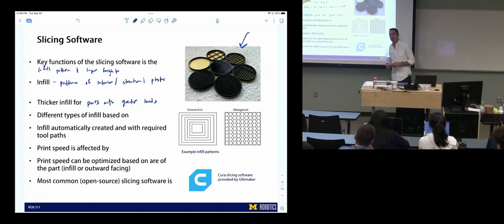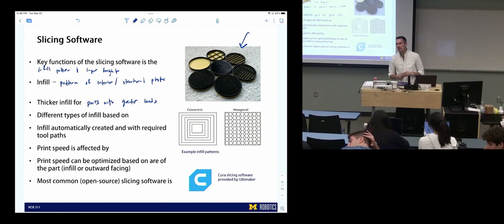So we have a ballbot we're making with acrylic plates and then a motor mount. You are designing the motor mounts. What infill do you think you want in the motor mounts? A lot or a little? A lot. So the motor mounts are going to have a lot of infill. I think we made ours solid. Is that true? No. Do you remember the infill percentage? 57, 50. Okay, cool. All right, so just a few examples of infill.